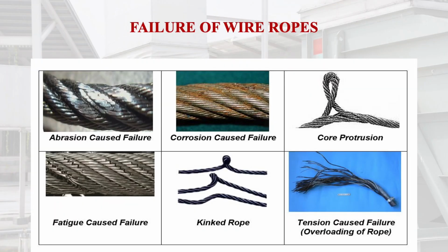Because this abrasion is normally ignored, sometimes the length of the wire is too high and there is pressure of the job, as well as the operator continuing to do routine activities. Therefore this defect is overlooked and there may be failure of the wire rope due to abrasion.